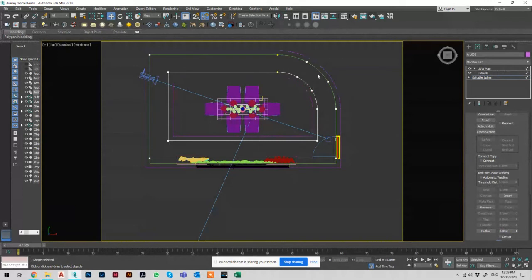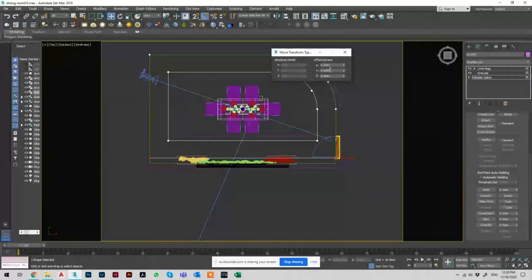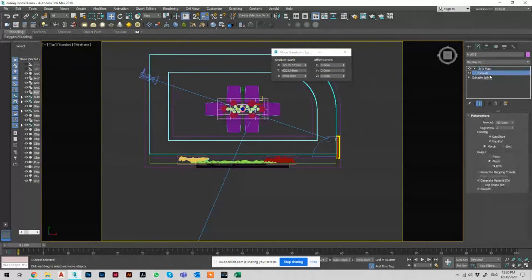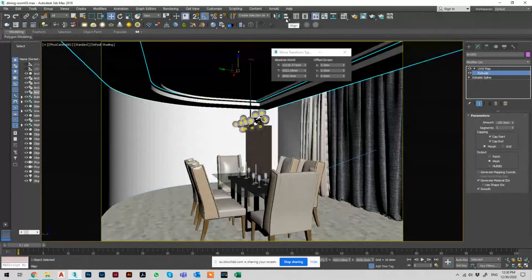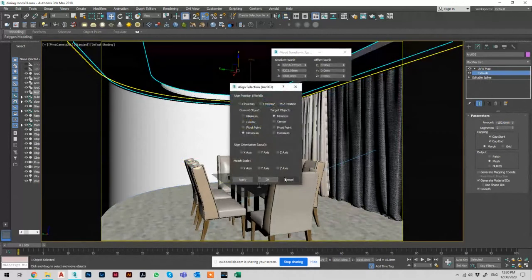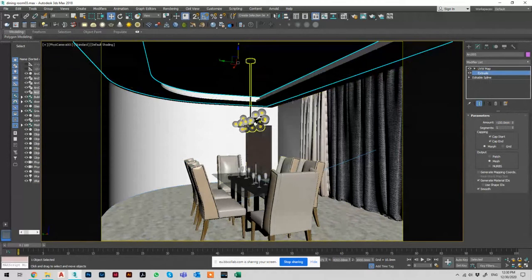Okay, so this is in the copy itself. And then if you want to add lights here, hidden light for the curtain, you can select these 2 vertices and again move them in the y-axis 200. So now I have this part. The extrusion is supposed to be 150. Let's just make sure that we align it to the ceiling. So it will be this way.